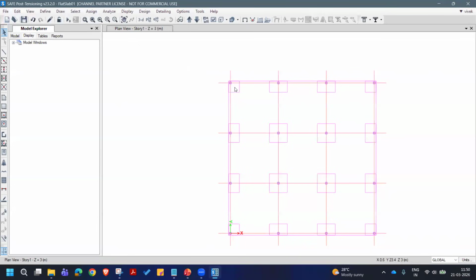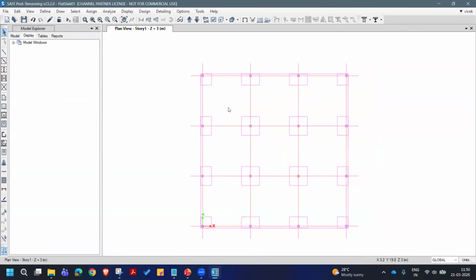And now what you see is just a layer of that drawing in the CAD program. Now this information you can find under the Model Explorer display tab. If I expand this plan view, you can see architectural layers, various layers are there used to create these. And for example, all the slab area objects have been created under this slab name.